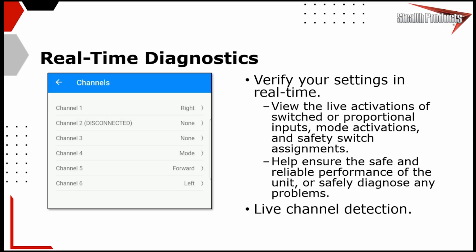Does it physically see it in that left port or the port assigned to left? If not, I likely have a problem with that input, right? Could also be the port. If I see something plugged in, I can go back to that diagnostic screen, see if iDrive's recognizing that input is sending a command. Again, if it's not seeing that, we maybe have a problem with that input.